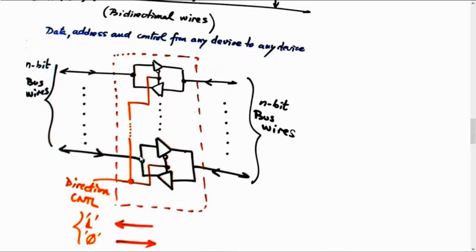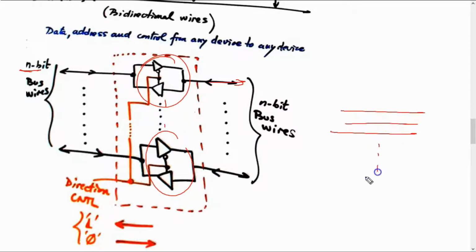So look at this. Here, now you have this two-state gate connection repeated 8 times or n times. The same architecture copied for every single wire, so that you can choose the directions of these bus wires, whatever you like, by means of a control pin.